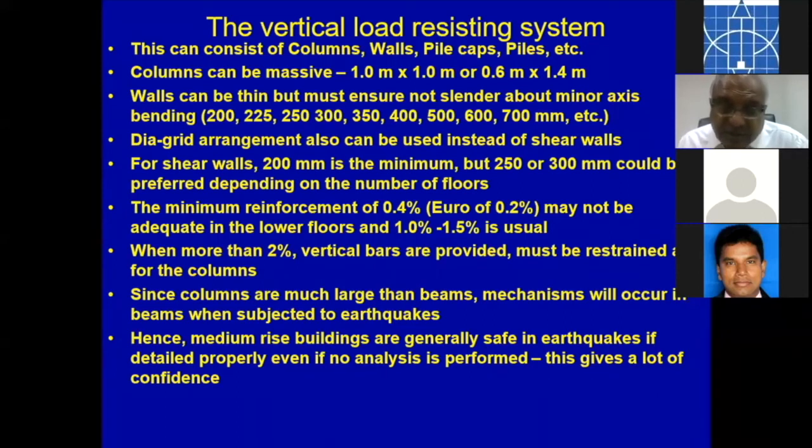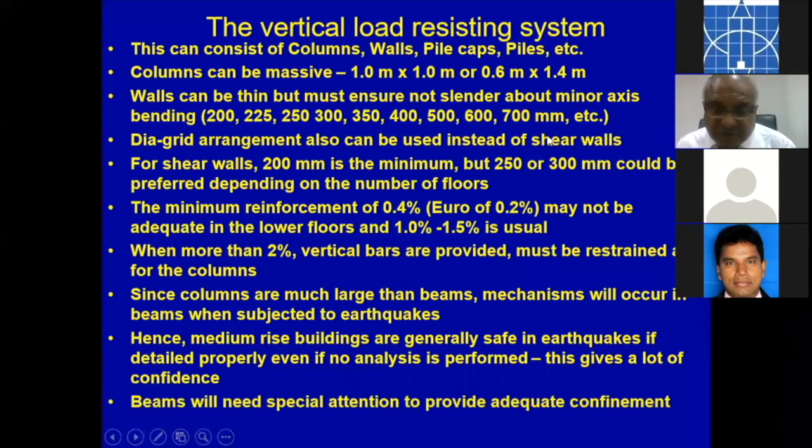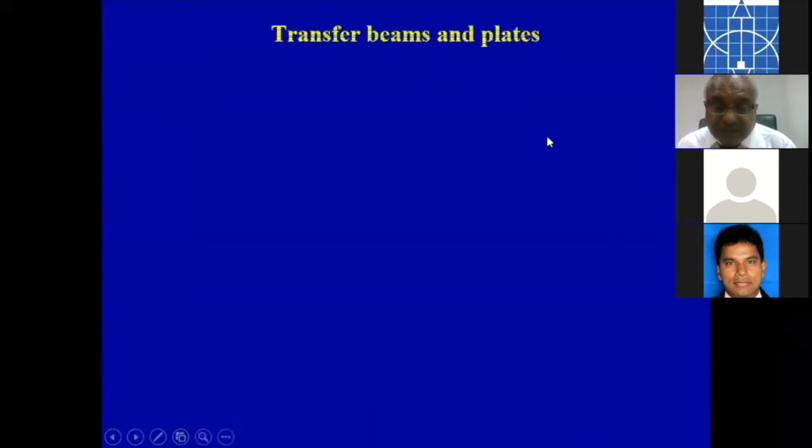The reason is a concrete wall is much more expensive than a column. The wall is long, so don't use concrete walls unnecessarily. If it is a say 15-20 story building, no harm in having a reasonable number of strong walls. But if it is a 5 or 6 story building, there's no need to have a concrete core, provided that you have done the design as for a unbraced frame.